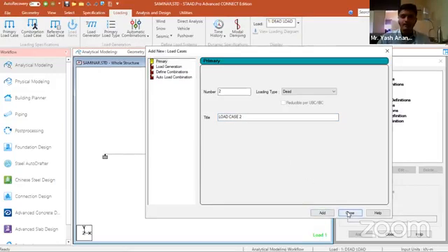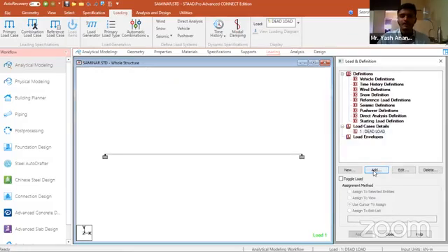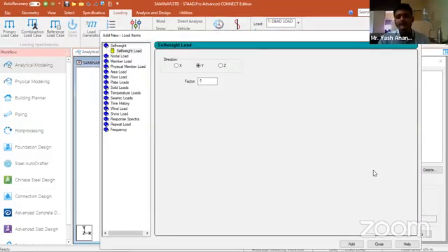Add. See, in dead load we are taking the self weight of the structure. Manually, we take the beam ISMB 600 and find in the IS code or steel table the weight for ISMB 600. That is okay where there is only one beam, we find it easily.